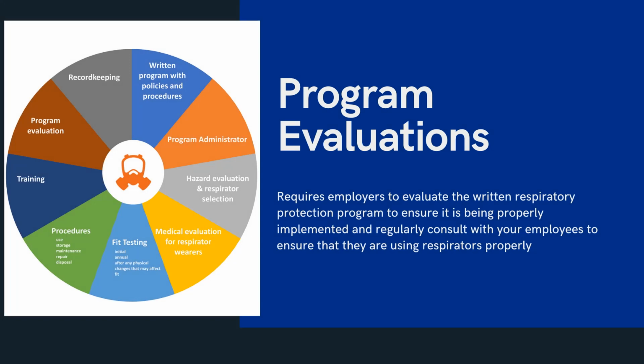Breathing air quality applies to atmosphere-supplying respirators such as supplied air and SCBAs. Compressed and liquid oxygen must meet United States Pharmacopoeia requirements for medical or breathing oxygen, and compressed breathing air must meet at least the requirements of Grade E breathing air described in ANSI Compressed Gas Association Commodity Specification for Air, G-7.1, 1989. The frequency of compressed air quality testing is not specified. It is recommended to test on a regular basis for liability reasons.